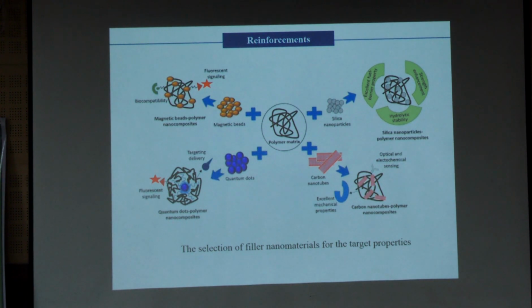But at the same time, if you reduce the weight of the vehicle, it means you have to replace the metal parts with lightweight materials. But if you are changing the metal part with some other polymer or any of the plastic, etc., then there is a chance of damage, right? That means the safety may be decreased. That is why nowadays all the parts are not replaced with composite, but some of the parts where we can reduce the weight and not impact the safety, those are replaced with composite materials.